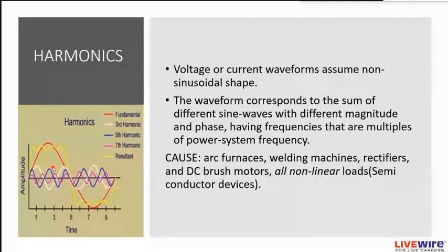Speaking about the causes of the harmonics, what causes the harmonics? There are many causes like arc furnaces, welding machines, rectifiers and so on. Generally, we can term the causes as all non-linear loads. All non-linear loads cause the harmonics to be introduced.